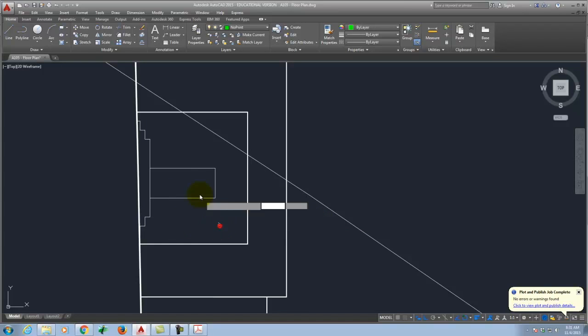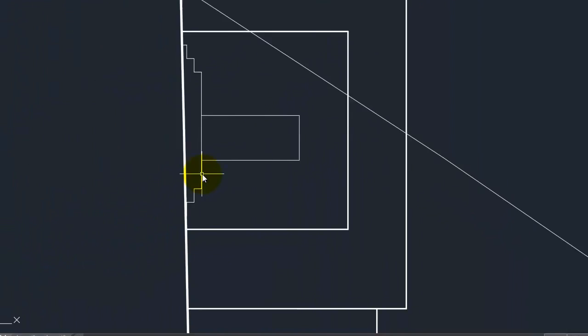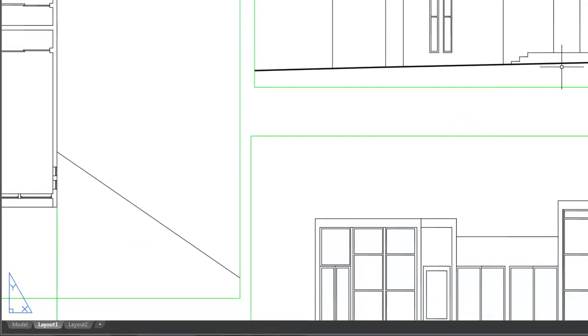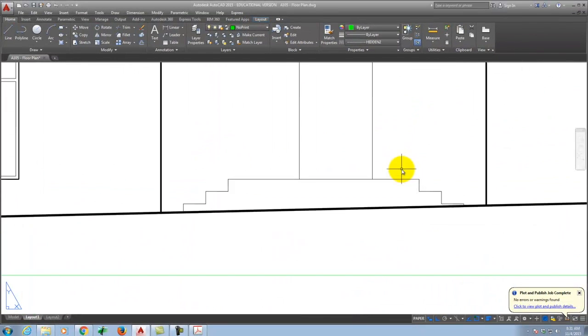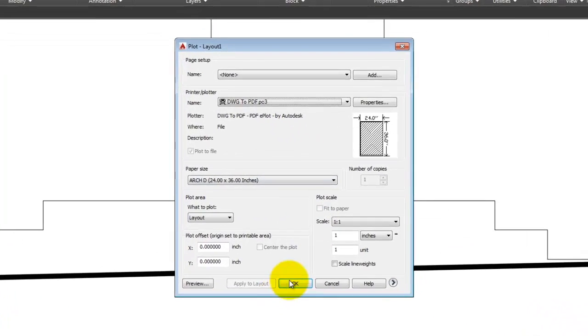And then I'm going to take these lines, and I'm going to change the line type of all of them to be that Hidden 2 line. As I said before, I can't see in Model Space that it is a hidden line. However, if we jump to the Layout 2 section, I'm supposed to be able to see it here, which of course I can't. Let me go ahead and print it and see if it shows up when it prints.